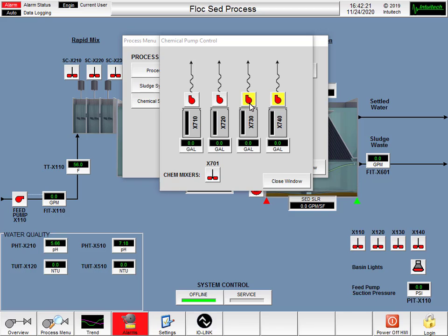Also, remember, for pumping chemicals into the system from the chemical tank, you will need both valves below the chemical pump to be in their down position in order for them to pump from the tank into wherever you have your chemical tubing put. Thirdly, please confirm the chemical compatibility of the chemical you will be adding to the system before you put it in the system. There are some chemicals that are incompatible with various plastics and metals.